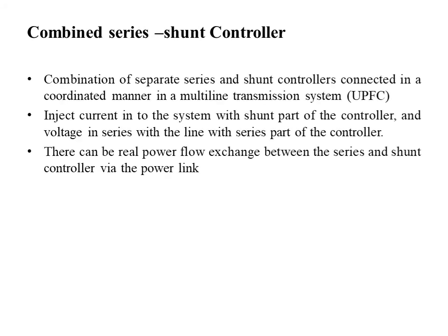Next, the combined series shunt controller: a combination of separate series and shunt controllers connected in a coordinated manner in a multi-line transmission system. One example is UPFC, which injects current into the system with the shunt part of the controller and voltage in series with the line with the series part of the controller. There can be real power exchange between series and shunt controllers via a power link.